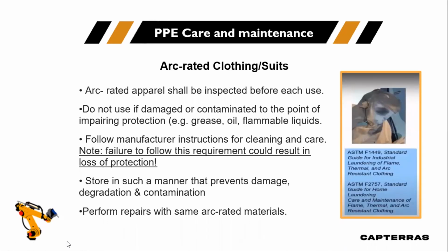PPE care and maintenance: arc rated clothing and suits. Arc rated apparel should be inspected before each use. Do not use if damaged or contaminated to the point of impairing protection, as an example, greasy or flammable liquids. Follow manufacturer instructions for cleaning and care. As a note, failure to follow this requirement could result in a loss of protection. Store in such a manner that prevents damage, degradation, and contamination. Perform repair with the same arc rated material.